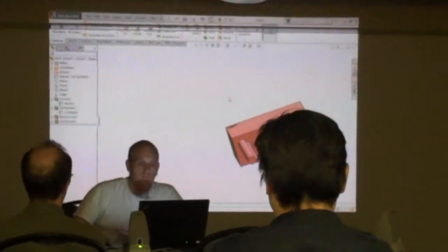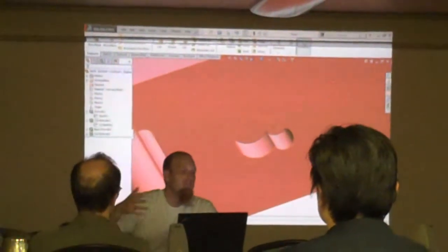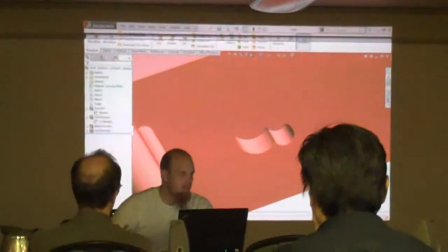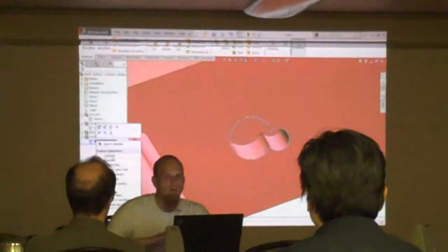Now, it's derived, you say, well, okay, it's great, I did want it all that way, but one of these guys in the design now needs to be different. It needs to be a different size. That's fine. We can come in and you can right-click and underive a sketch.